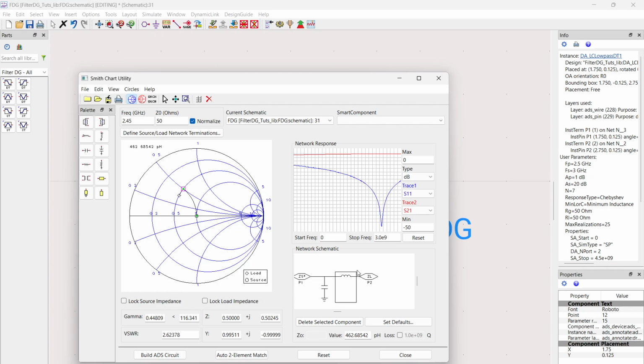Since this is kind of reciprocally designed, we want to set our capacitor or our inductor in series after the filter, and then we want to set the shunt capacitor, and we want to set actual real values. So you may have to adjust this filter moving forward since you're not going to find a 462 picohenry inductor. But this is how you can make some changes to it after you've seen the real values on a VNA.